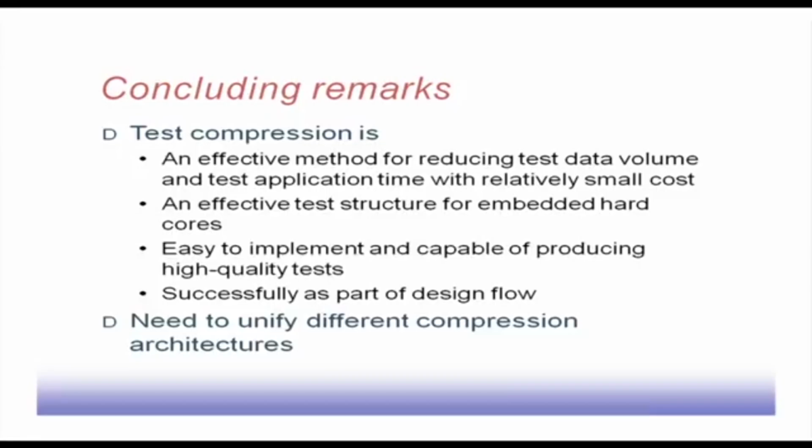In conclusion, test compression is an effective method for reducing test data volume and test application time with relatively small cost, because we do not need to use a more advanced ATE to store huge amounts of test data or apply the test at a higher frequency. At a low frequency we can transfer the pattern set, and then using a decompressor we can decompress the test patterns and apply them to the circuit. And then we can also do some response compaction.